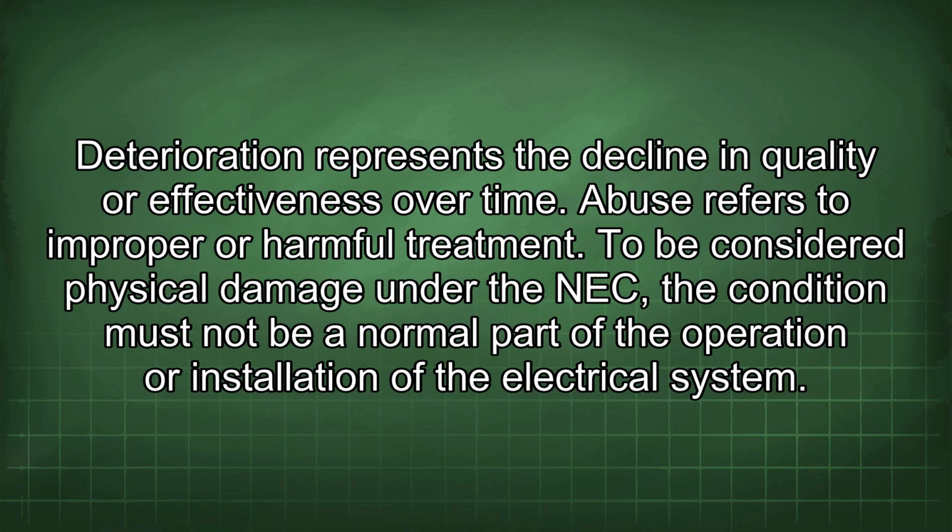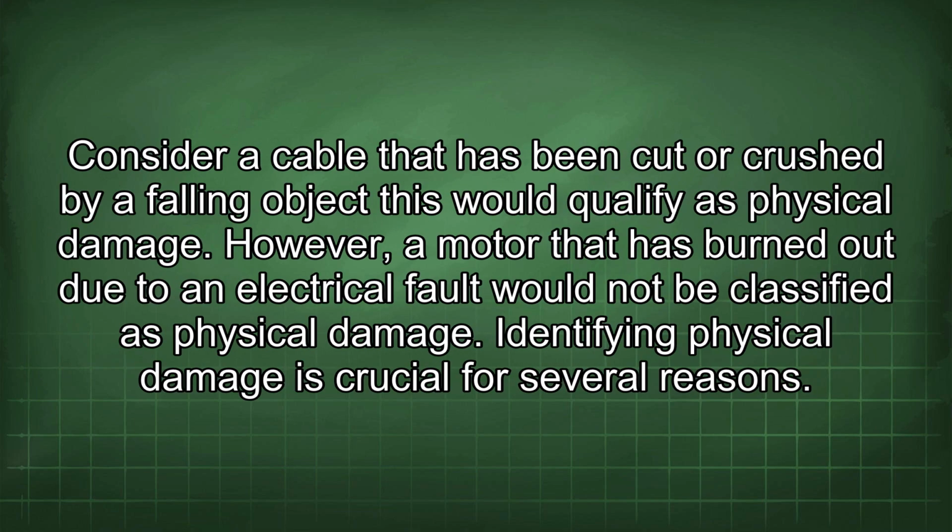To be considered physical damage under the NEC, the condition must not be a normal part of the operation or installation of the electrical system. Consider a cable that has been cut or crushed by a falling object. This would qualify as physical damage. However, a motor that has burned out due to an electrical fault would not be classified as physical damage.